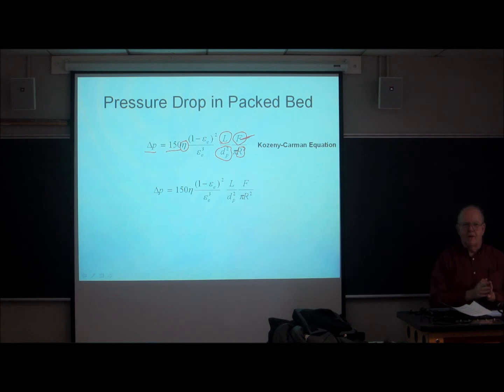And every time we drop the particle diameter a factor of 2, the pressure drop needed to push stuff through those beds goes up a factor of 4. And this is what accounts for the increase in the pressure from 400 bar to 1200 bar over the past few years. The change from 3 micron particles to 1.8, 1.7 micron particles has crossed that barrier, and we've had to increase the pressure. Why is this a big deal?